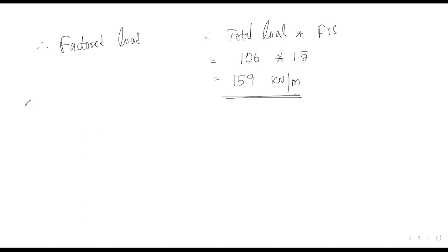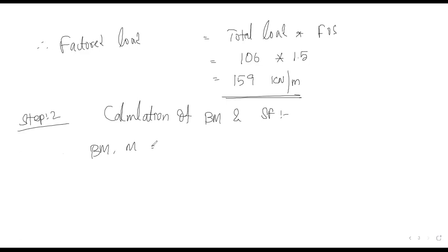Now we go to step 2, that is calculation of bending moment and shear force. First, calculation of bending moment M. Here it is simply supported with UDL throughout, so the moment value becomes WL squared divided by 8.